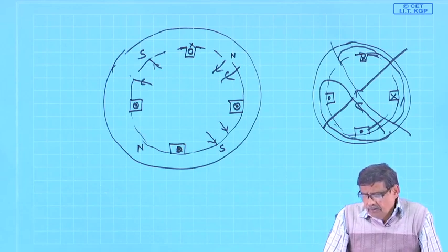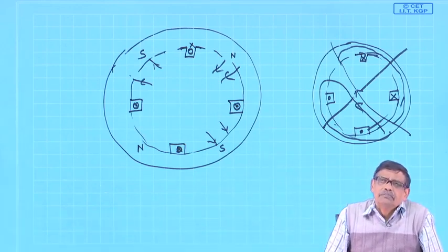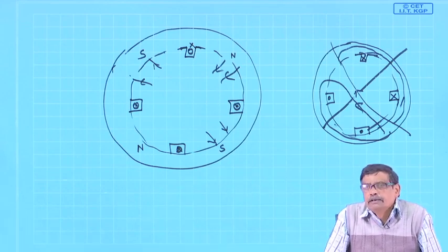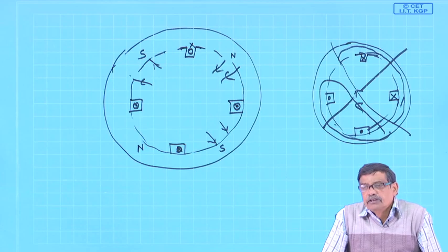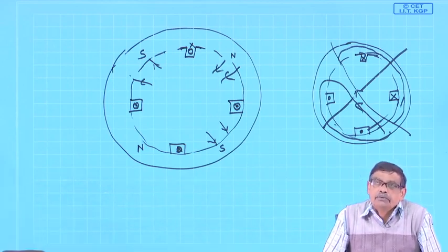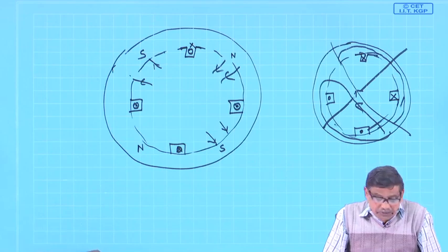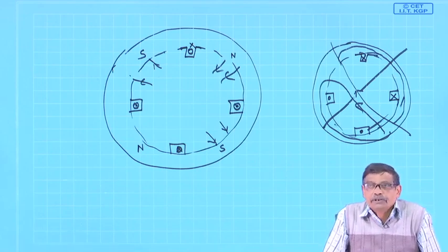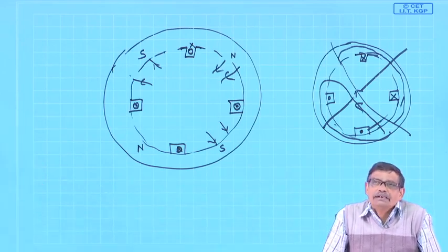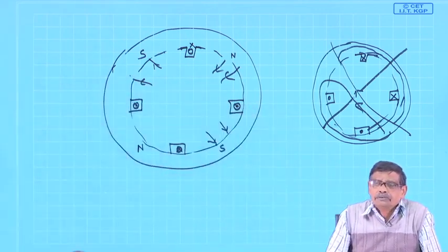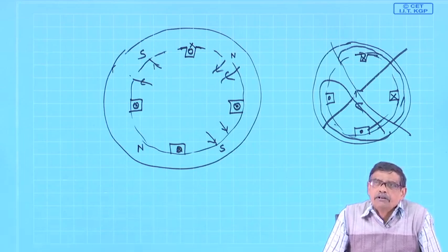But with the passage of time, those methods are nowadays no longer used, because with the advent of fast switching solid state switches, you can make a good inverter and you can vary the frequency of the supply to control the synchronous speed of the induction motor, hence its speed, which is much more elegant and easier than asking for 2 separate stator coils or one 3-phase stator coil with extra terminals brought out, which always had to be reconnected in a particular fashion to give different levels of speed.